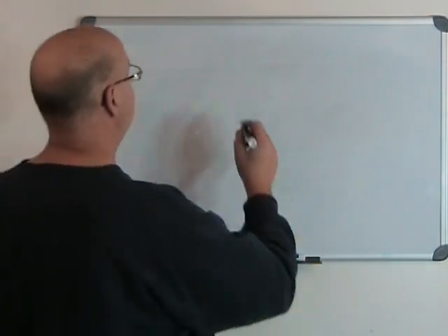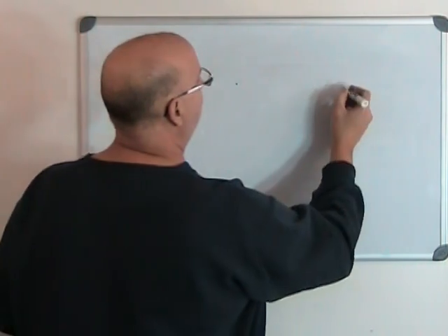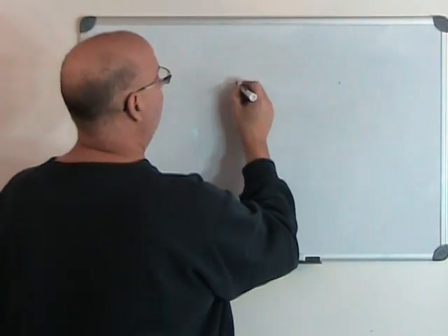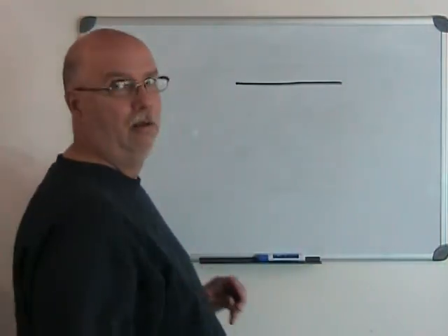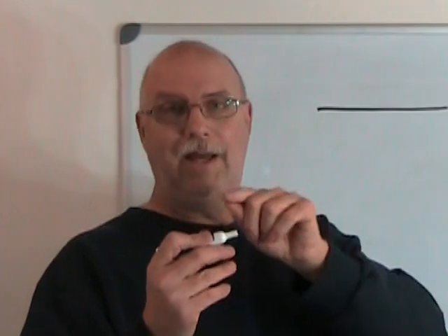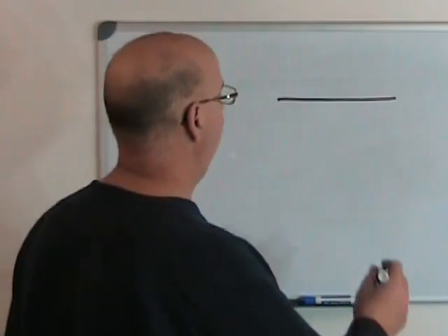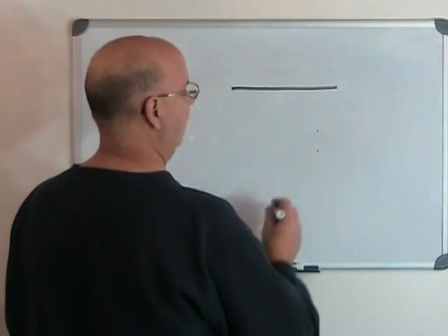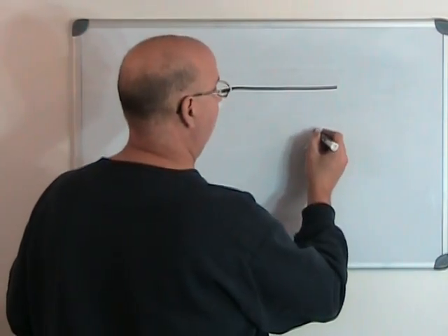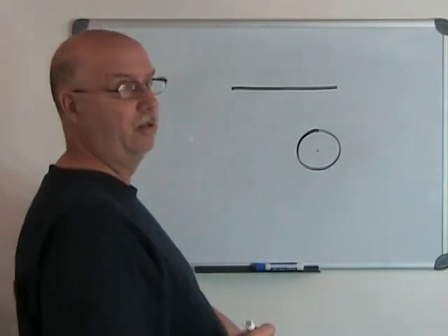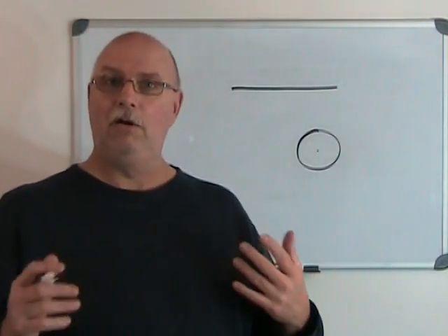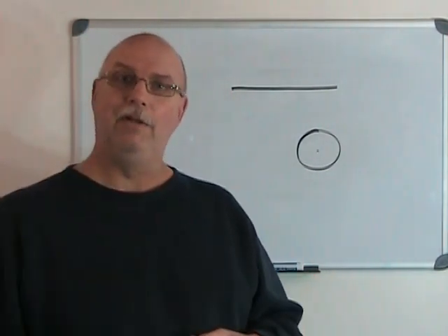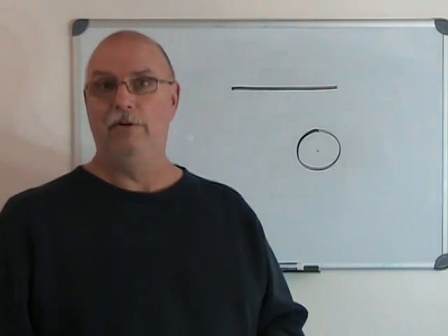So, take a look and see. At my start point, my finish point, I place, and I go. Just that simple. For the circle, I'm going to use the same approach of avoiding looking at the tip of my pencil. I'm going to mark the start point, I'm going to mark the center point, I'm going to position myself, and then I'm going to draw my circle. Freehand, quickly, without looking at the tip of the pencil. It's the best way to do it.